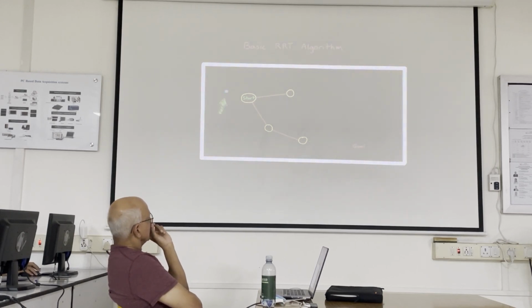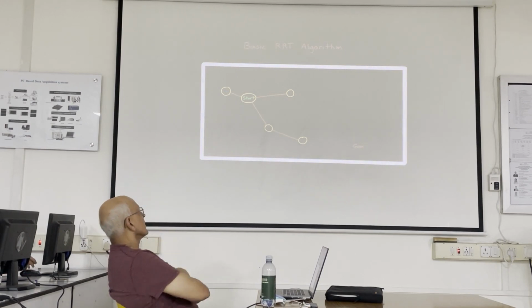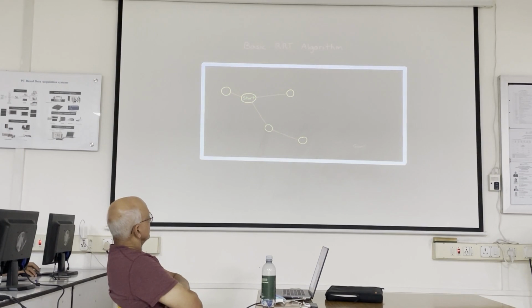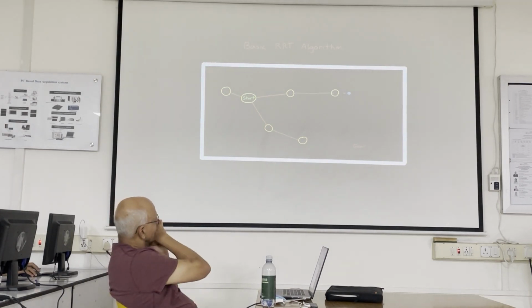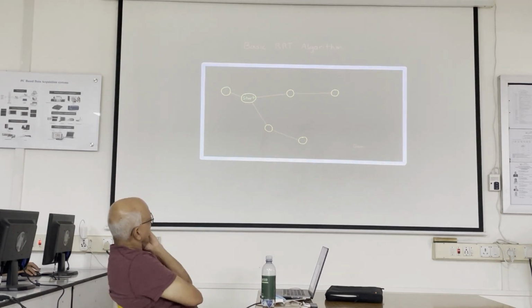And a random node that is in a direction opposite of the goal doesn't affect the path that's on its way to the goal, since a different node would be nearest. In this way, one path is always rapidly making its way towards the goal, and the others are rapidly making their way into other open areas of the state space. And then later on, as the unexplored area starts to fill up, the random node selection tends to just fill the tree out with more branches.